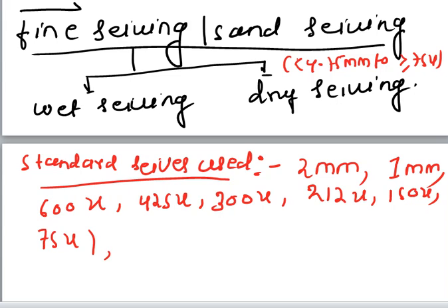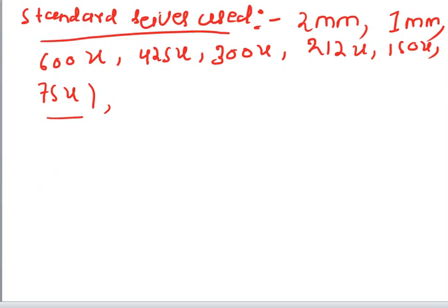So these are the standard sieves, and the procedure of sieving is exactly the same. You have to sieve at least for 10 minutes, and it can be done in two ways, either mechanically or manually. That is the procedure, and the aim is to find the percentage finer only, in the sand group. Now we have to understand why there are two classifications, wet sieving and dry sieving.